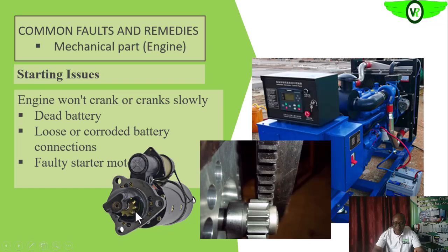So while it is pushing the pinion gear forward, it is sending voltage or power to the starting motor to cause the turning of the shaft. As the pinion is moving forward, the power is delivered to the motor and then it will start turning. So that is the function of this solenoid.